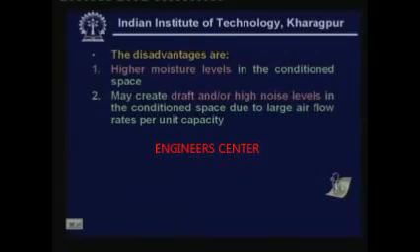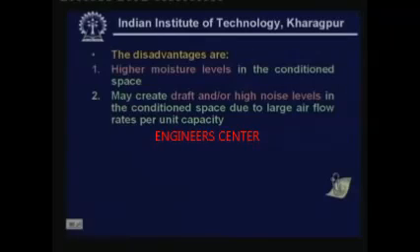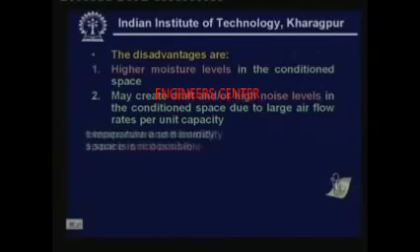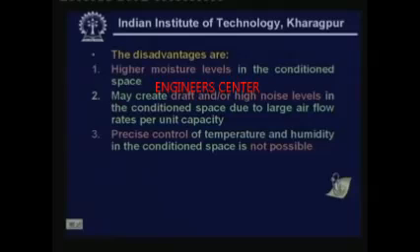These systems may create draft or high noise levels in the conditioned space due to the large airflow rates involved. Since you have to deal with a large airflow rate inside the fan, it may create a large noise. If the flow rate is high, you may also have the feeling of draft. This could be a disadvantage from the comfort point of view. Another disadvantage is that precise control of temperature and humidity in the conditioned space is not possible. Whereas using a conventional system, you can precisely control the temperature and humidity inside the conditioned space.